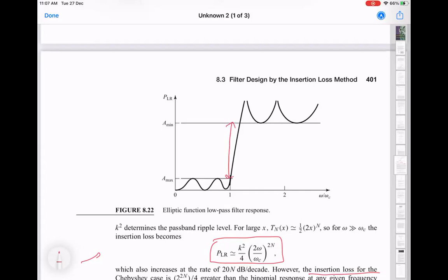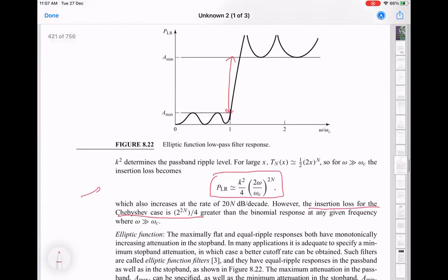So this is again a different optimization where you say that I want my filter to at least reject by a factor of 10 or a factor of 20 between the pass band and the reject band. And then there are some frequencies where the rejection is much better, but the worst rejection is at least at this value. Okay, so this is another optimization called the elliptic design. Again, in practice, I've never really seen this